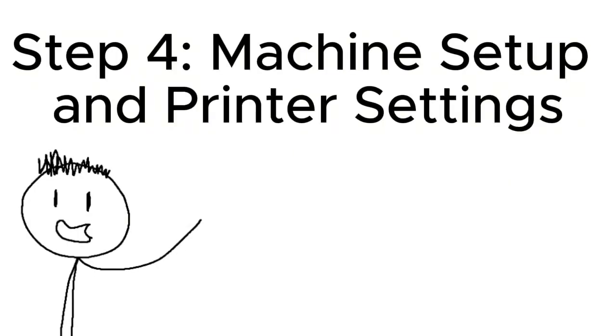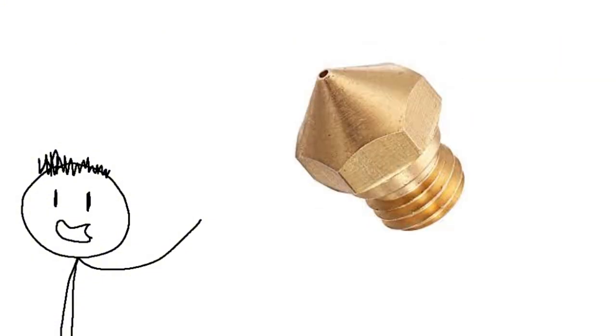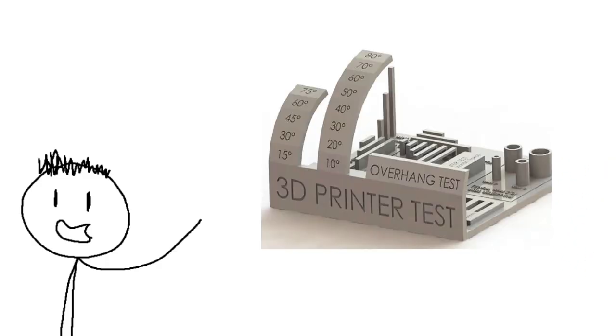Step 4. After slicing, it's time to prepare the printer. This includes loading filament, preheating the nozzle and bed, leveling the surface, and adjusting temperature and speeds. If you just set up your printer for the first time, you may want to run a test print to make sure everything's working smoothly.